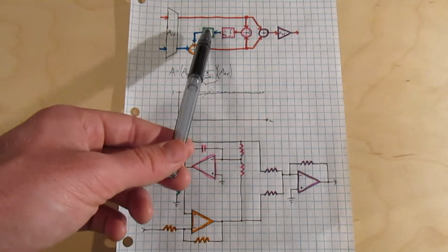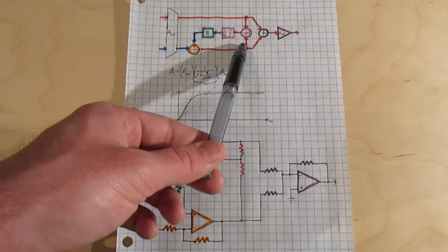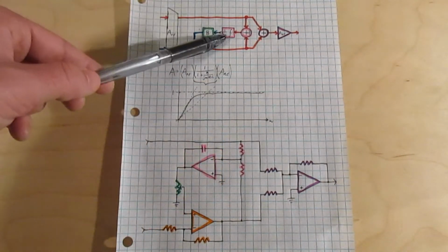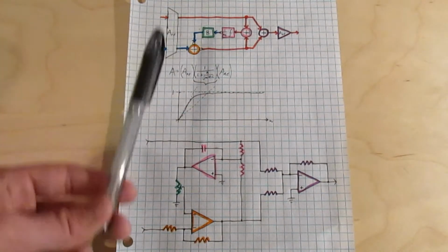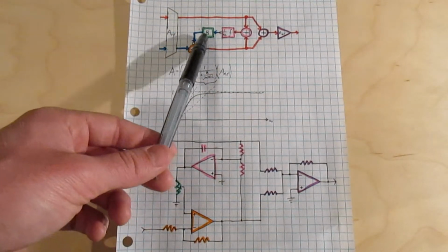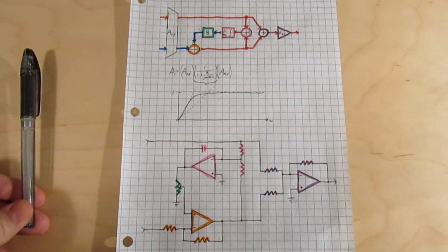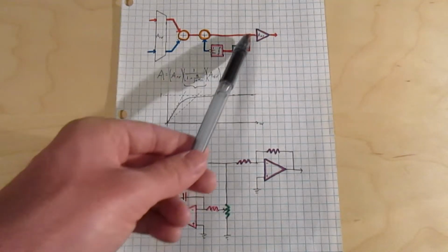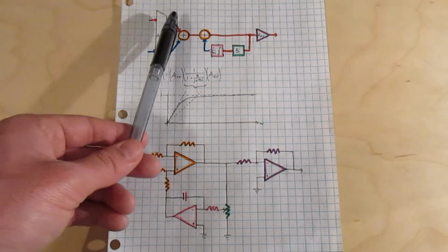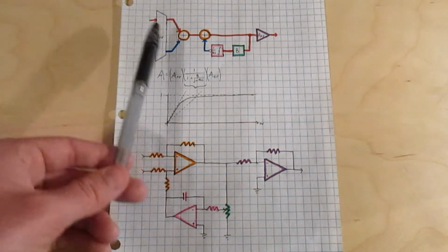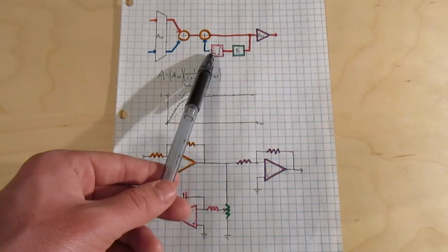I could move the attenuator to the input of the integrator, and that would solve that problem, but the input to the integrator is differential, and I couldn't really think of an elegant way to move the attenuator over to the input. And that's why I came up with this. The DC offset tracking is not done in the differential part of the circuit anymore, which means I can put the attenuator at the input of the integrator.